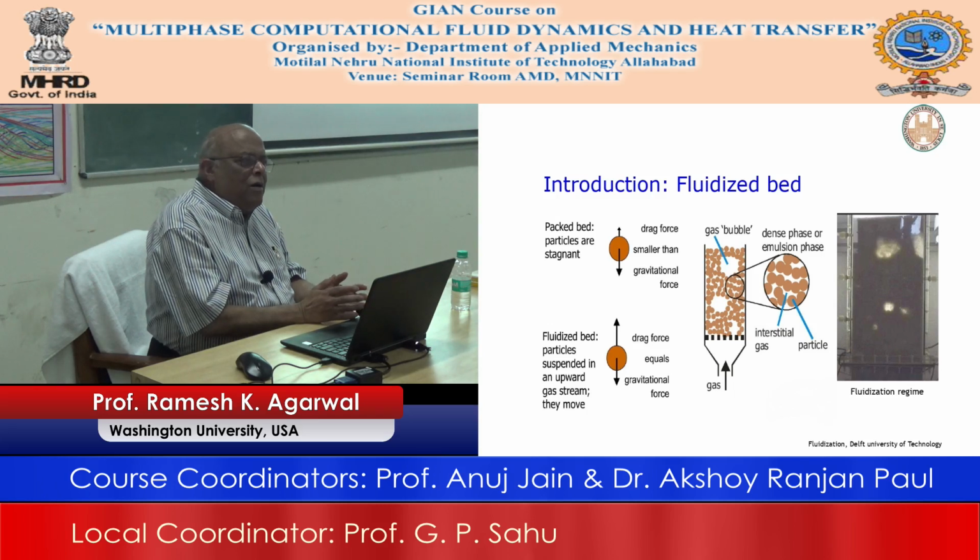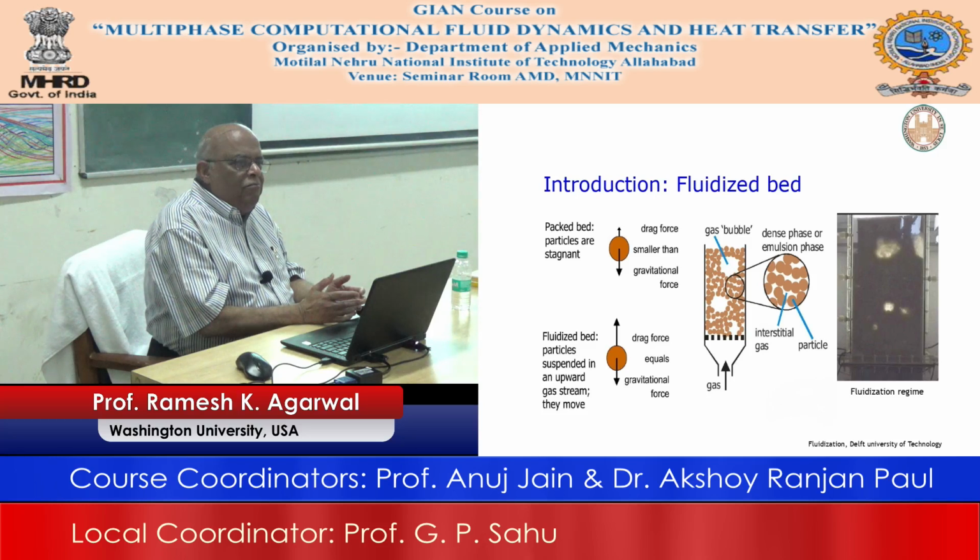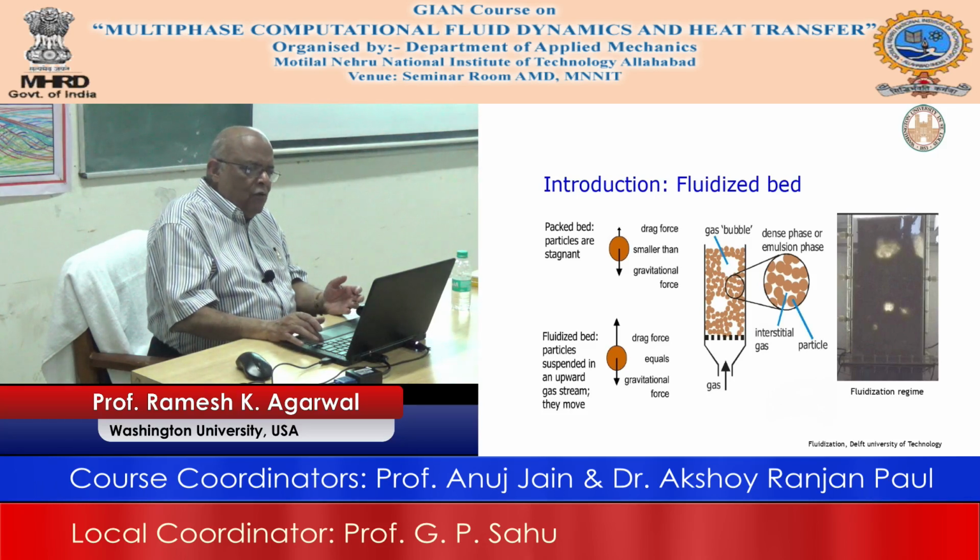There is hydrodynamics because of the gas, and there are particles because of the solid. So it is a solid-gas problem. You can use a two fluid model if there is a very small amount of coal, or you can use a DEM. Then you have to use the parcel approach to make it possible.